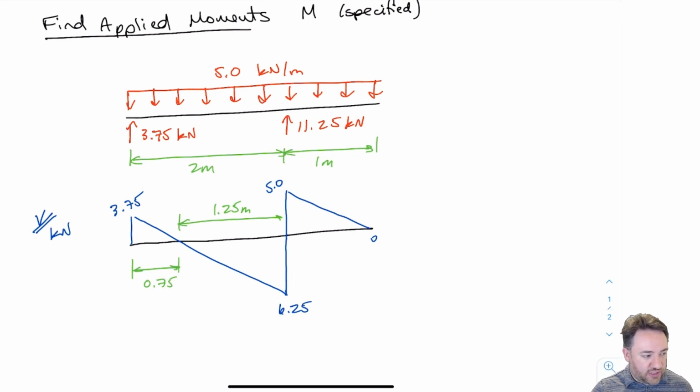But if I was doing this problem for glulam, and I need to calculate my KZBG, my size effect factor, remember that it's the tension segment, the segment of the beam between zero moment locations, that is what defines my length for calculating size effect. So I'm going to need those lengths in general. Okay, so now if I want to calculate my moment,